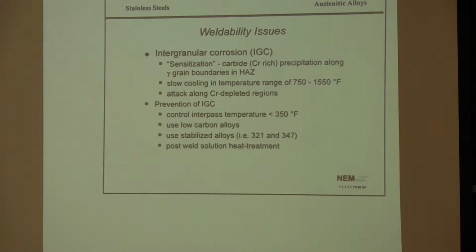What happens there is the carbides actually form preferentially with the titanium and the niobium instead of the chromium, and so the chromium is left behind, and you end up with titanium and niobium carbides at your grain boundaries, and that doesn't lead to that zone that is susceptible to corrosion.